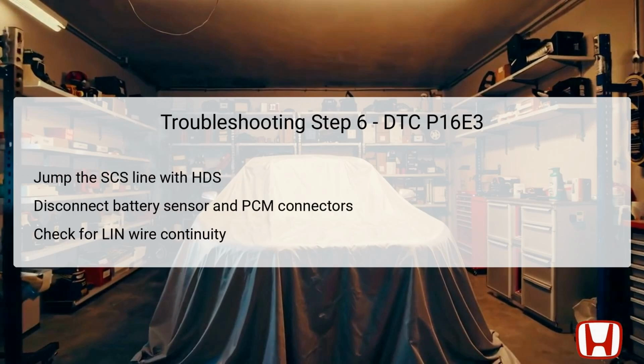Step 6 requires repeating the initial step of jumping the SCS line with the HDS, preparing for continuity checks on a more extensive level. Disconnect both the battery sensor 2P connector and the 49-pin PCM connector before proceeding. You will then check for continuity between the specified points on the automotive communication line. Specifically, check between PCM connector B terminal number 16 and battery sensor 2P connector terminal number 2.